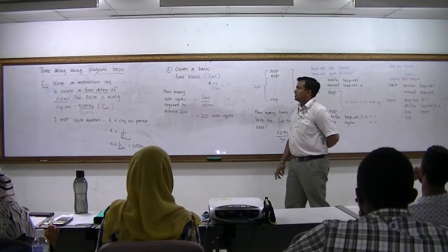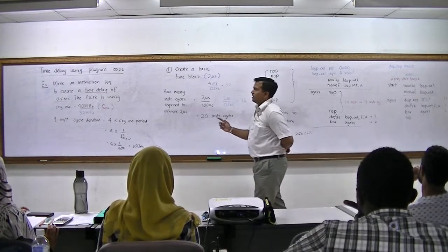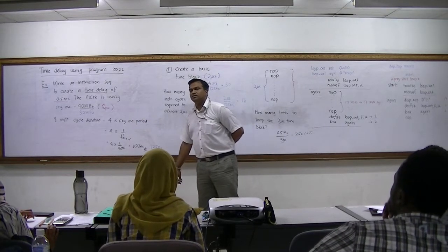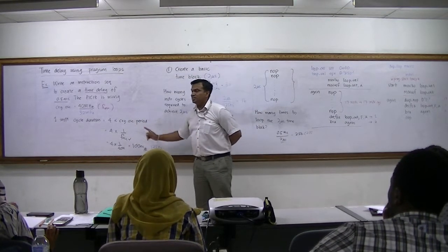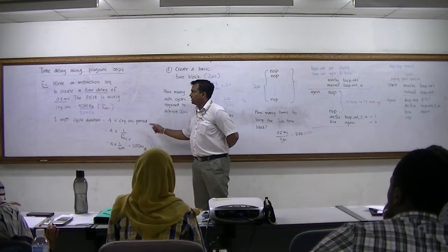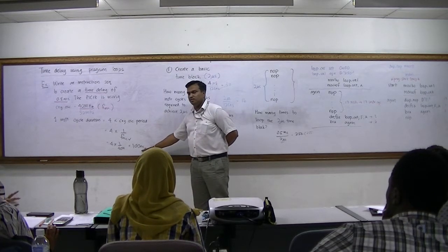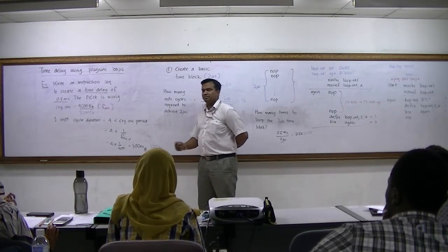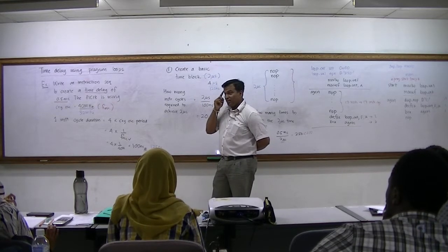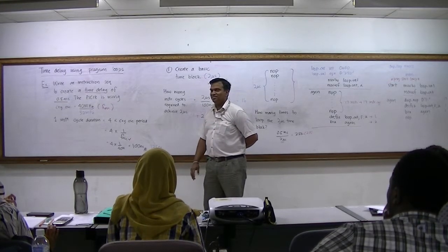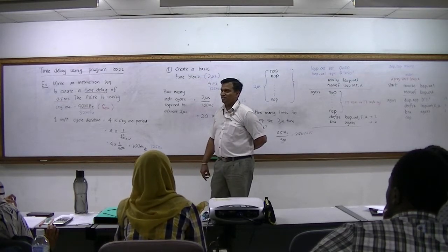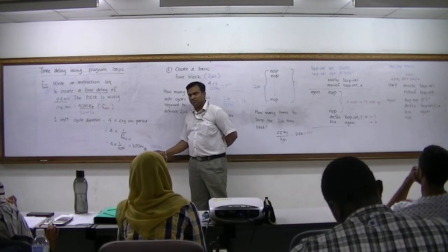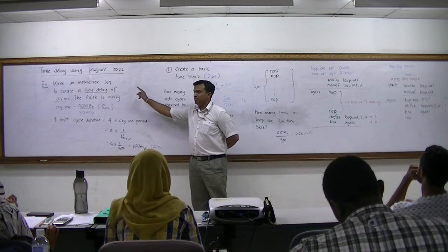Is that okay? So we have changed two variables, right? One, the crystal oscillator. When the crystal oscillator changes, what will change? The duration of one instruction cycle will change. The higher the frequency, the faster it will be. This is actually true. So which one is faster? This one is faster. 100 is faster. Don't get cheated with a bigger number. Remember, in time, the smaller the number is faster. So 125 means it's taking longer than 100. You understand? So the higher the frequency, the faster it will go.